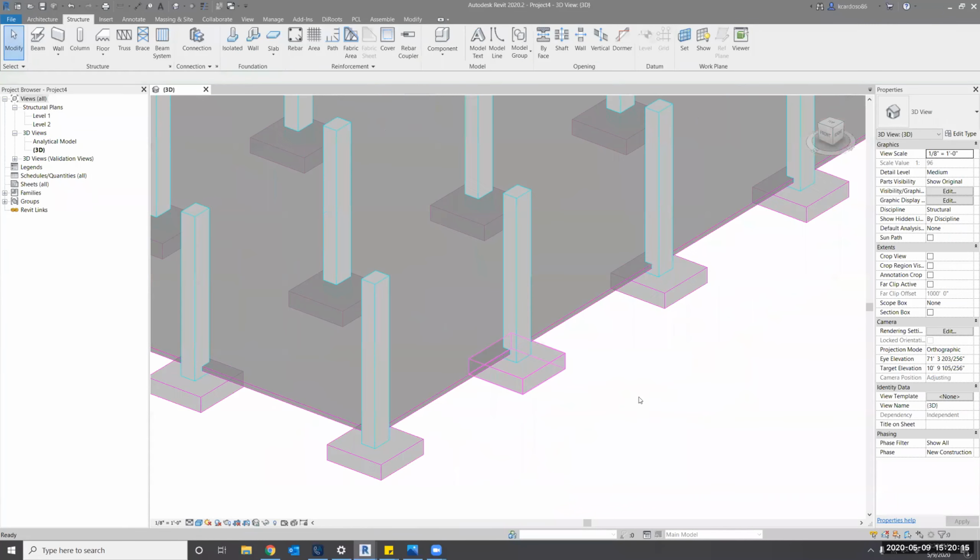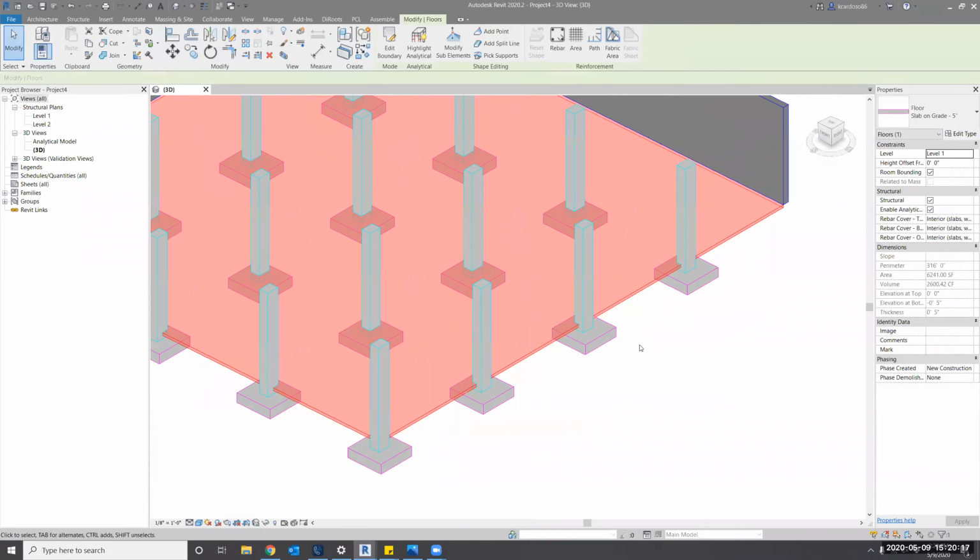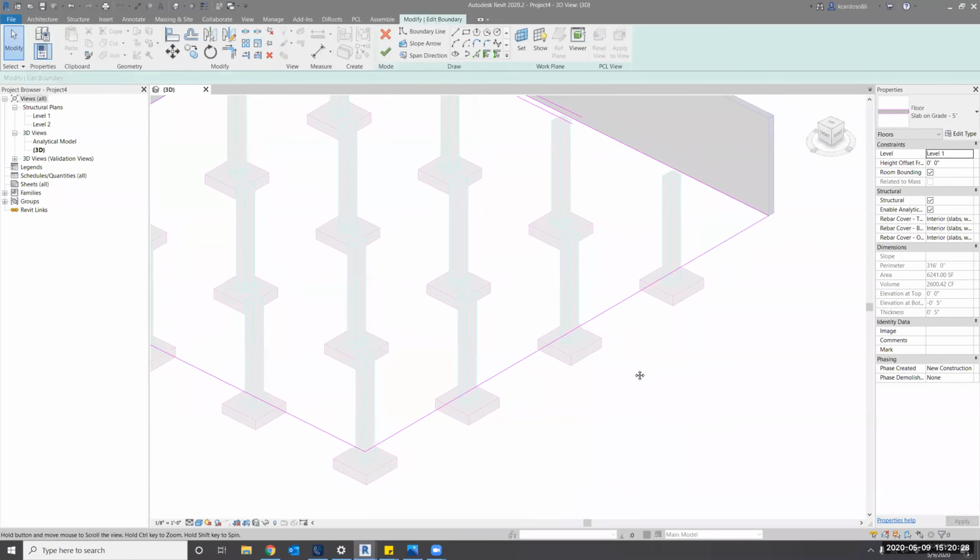So one thing that I want to add in here is a little arc on this floor. So do not go to level 1. All right, let's make it here. Let's double click on the floor, and on your drawing tools up here, let's select this guy right here. Start and radius arc. Click anywhere, and just add an arc to this.